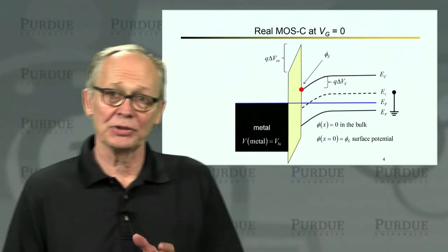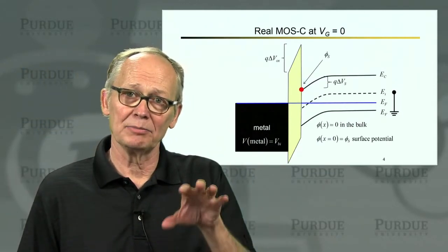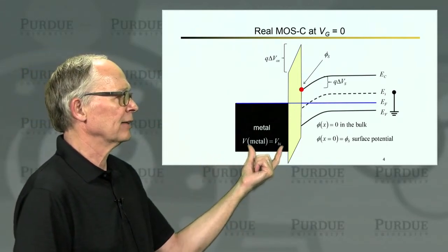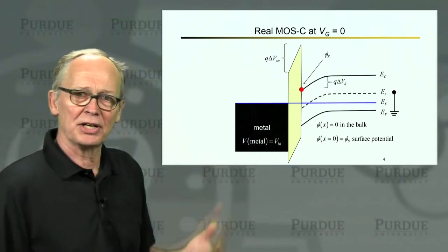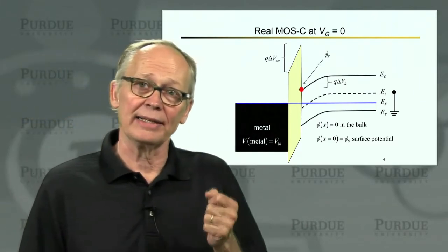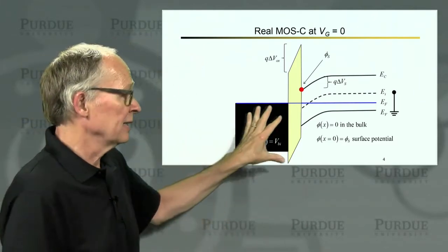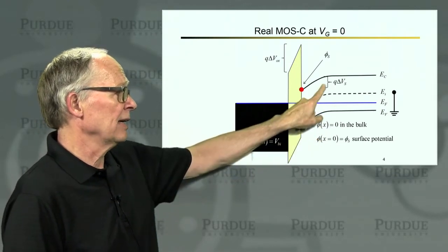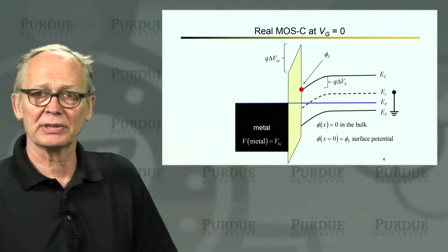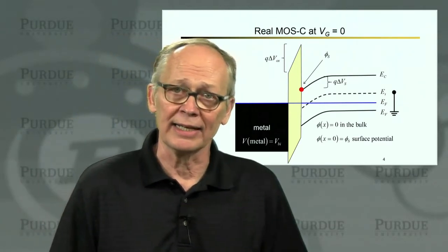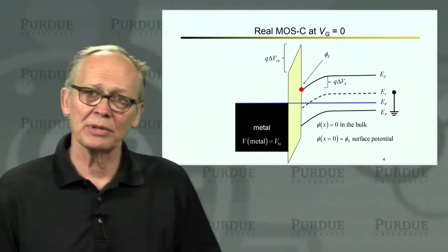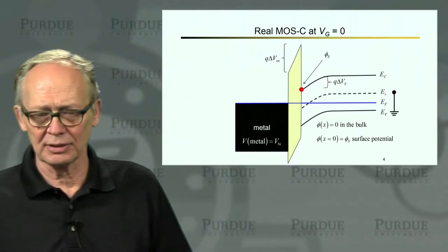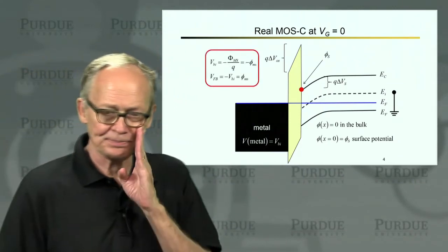Okay. Now we put these two together, we said a positive built-in voltage has to develop on the metal. That's this V_BI here. If there's a positive voltage on the metal, before I've applied any positive gate voltage, then that positive voltage is going to cause the bands to bend down, and we will have some positive surface potential before we've applied any gate voltage. So that's the situation in a realistic structure with work functions like those that we've shown.